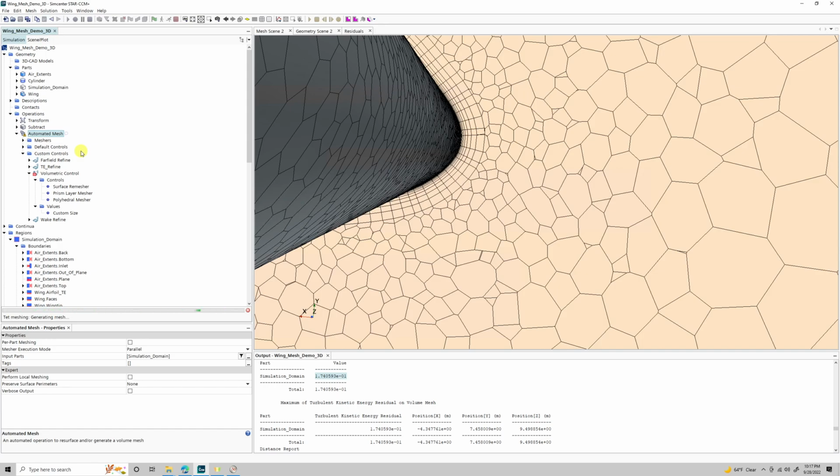The problem with volume controls is if you take a cube and you break it into edge lengths, if you break the edge length down by a factor of 2, you're not left with 2 cubes. You're not left with 4 cubes. You're left with 8 cubes. So if you're not careful with volumetric controls, your cell size can absolutely explode on you very easily.